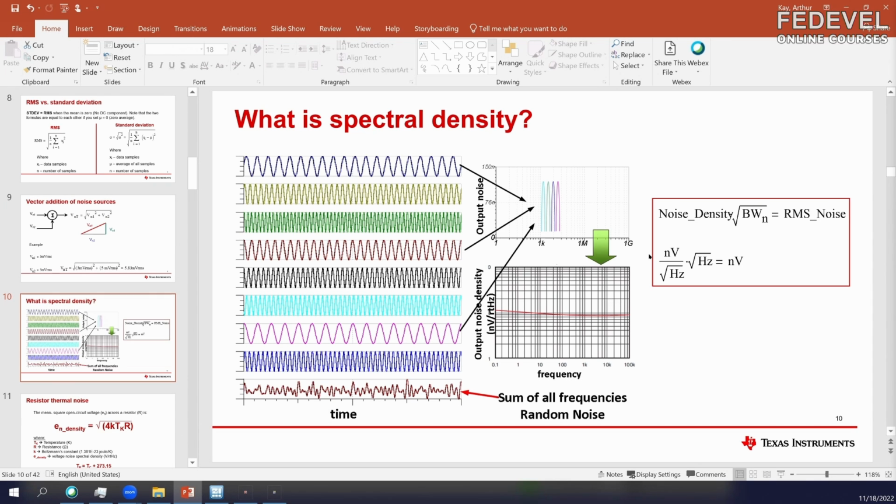Yes. And I mentioned that if you wanted to hand calculate it, you would take this curve's magnitude and multiply it by the square root of the bandwidth of the circuit. The bandwidth of the circuit is what's limiting this. Okay, let's go back. We can continue.